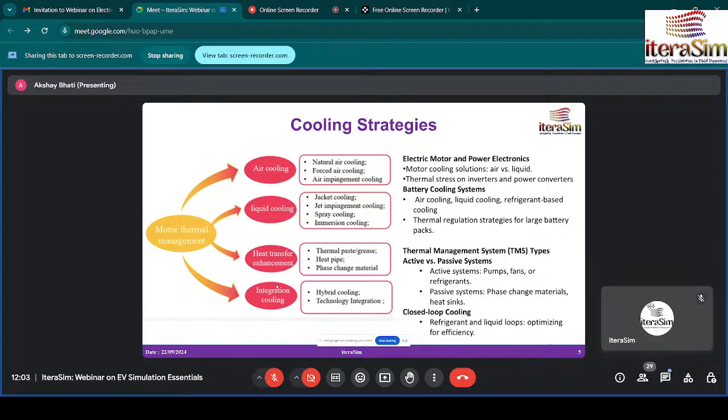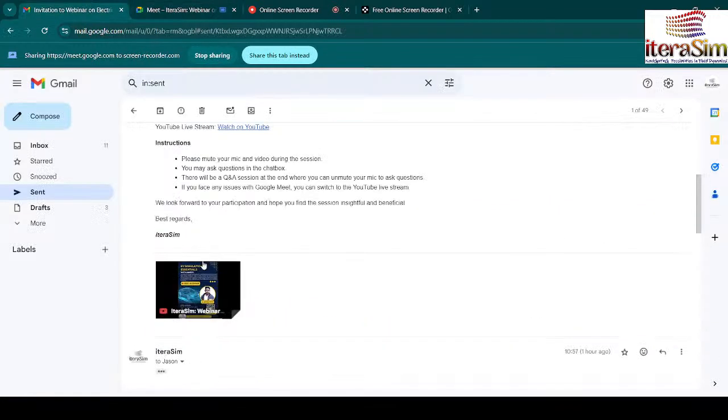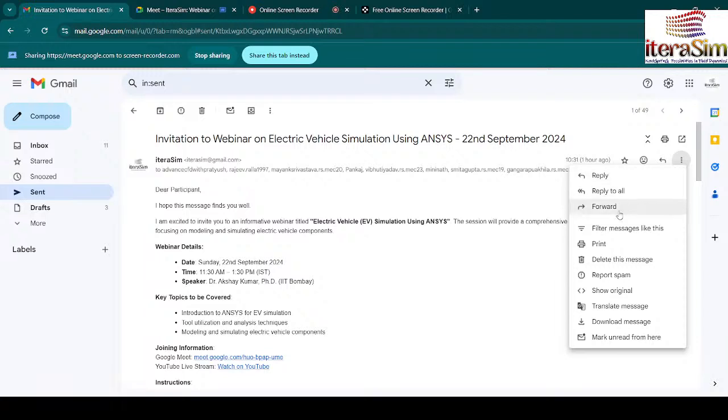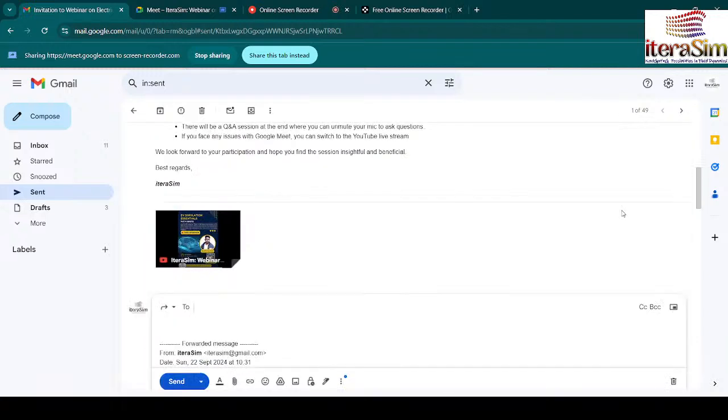So that is the advantage of spray cooling, that it is a space saving cooling, requiring less physical space compared to bulk cooling systems like chillers or large heat exchangers. So if we want to develop a compact electrical or electronic system, a high performance system generating heat continuously at very high flux, it will work as a space saving solution, and it can absorb more heat in lesser space, and it can be easily added to various applications and scales. That is also one benefit.